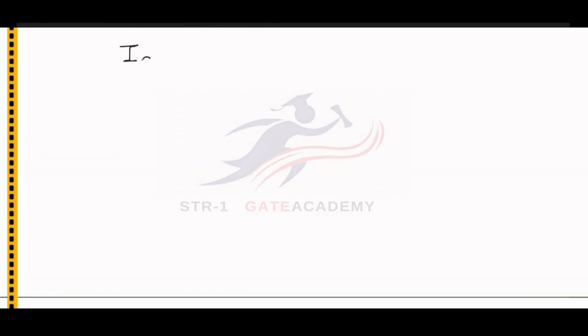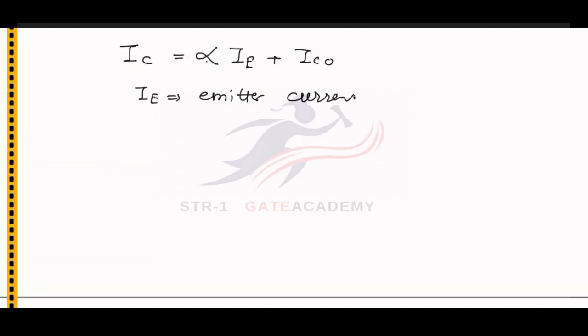Also, the equation for collector current IC is given by IC is equal to alpha IE plus ICO. Alpha we will discuss later. IE is emitter current, and ICO is called collector reverse saturation current.